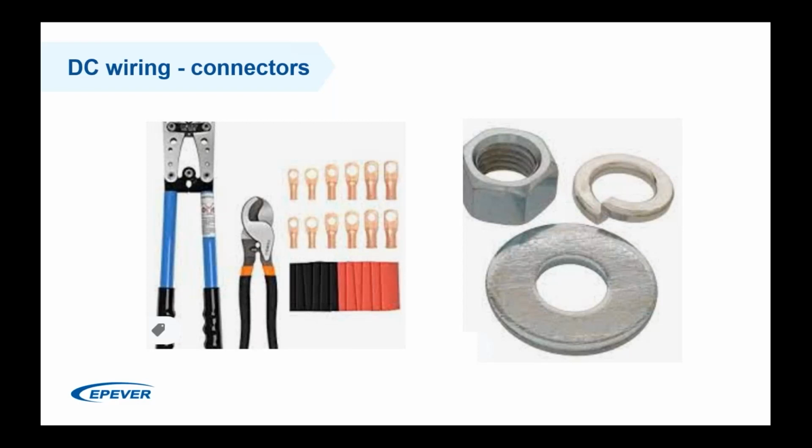So if you tighten one too much and the other one a little bit loose, then the area that the locks connect to the bus bar are not the same, and then there is a difference in the resistance level, and this is called the improper balancing of your batteries, for example.